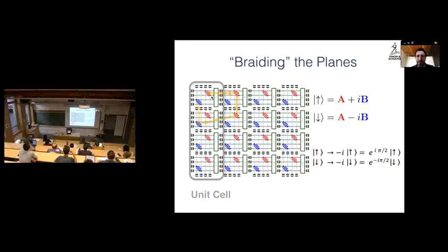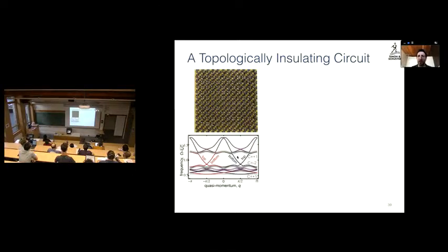Onwards. So we can build this whole lattice of these things. I showed you what the lattice looks like, and you can then compute a band structure. So here's the first question for you. I maybe shouldn't have shown you the answer first. But how many sites are there in a unit cell for this lattice? Where a site is a pair. These two inductors, two LCs, is a lattice site.